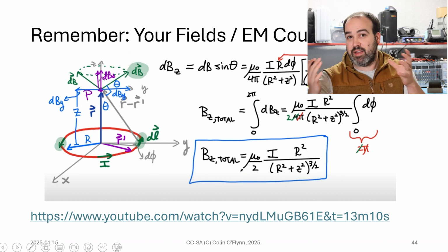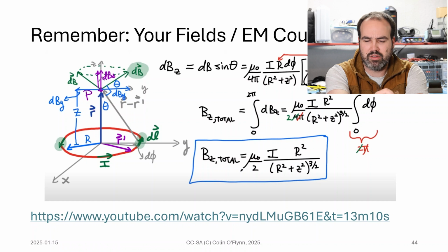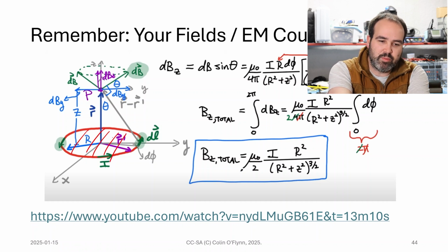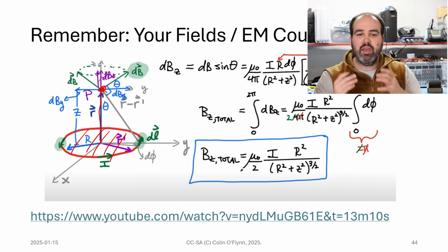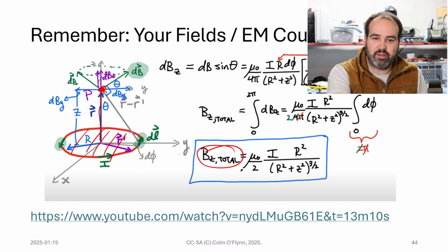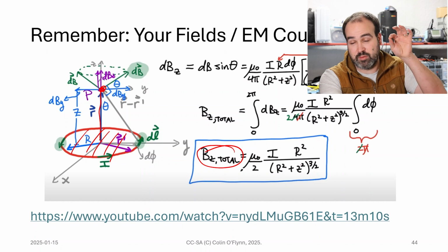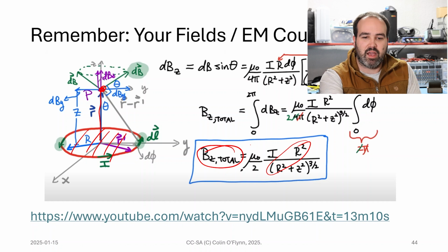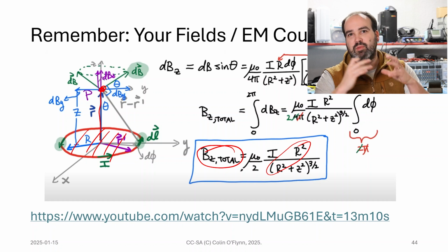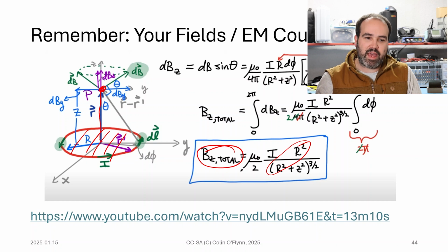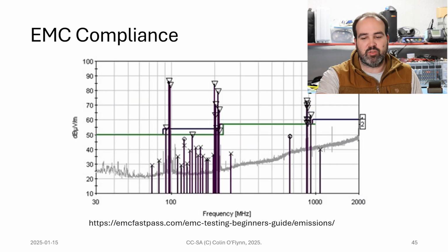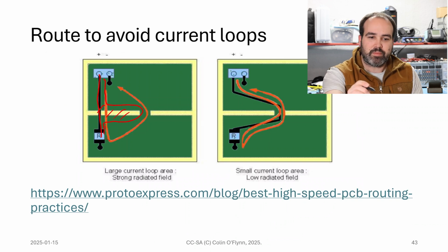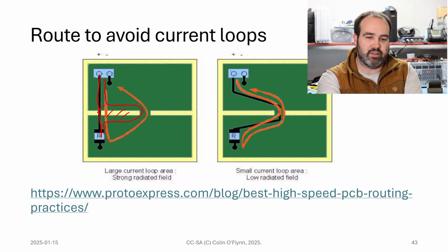And this loop means you have stronger emissions. And this is, at Dow, there was an EM Fields course they should have taken. This loop basically means that you have a larger loop area. If you look at a point far away from a loop, the magnetic field at this point in space, not time, is going to depend on the area, aka the radius, as well as the current through it. But as the radius goes up and the area goes up, that field becomes stronger.